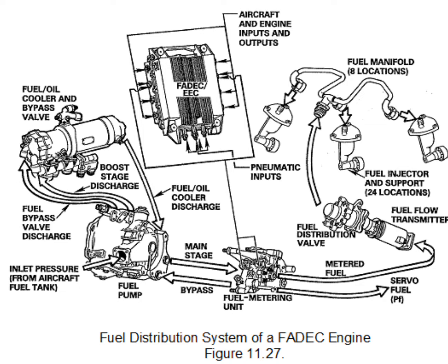What are two types of electric fuel controls for turbine engines? EEC and FADEC. What is FADEC? Full authority, digital electronic control. Does a turbine engine controlled by a FADEC require manual trimming? No. FADEC is self-trimming.